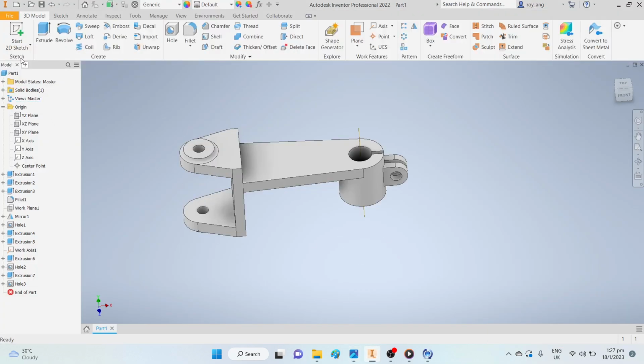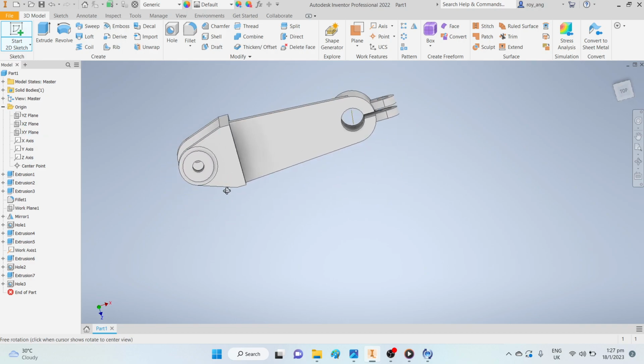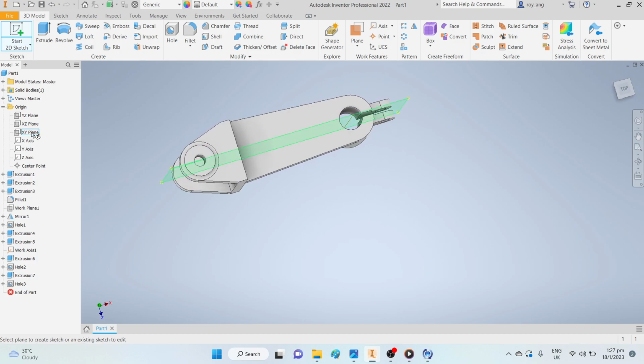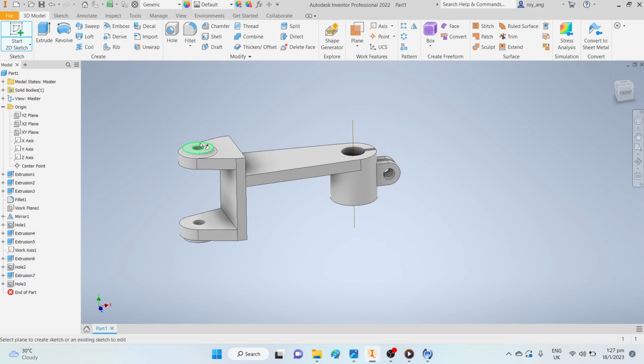How I will do it is I'll first create a sketch, and I'll sketch on the XY axis. Okay, the XY axis runs right through the center of the part, so that's where your work plane is, right? If you were to create a mid plane just to create the rib, you will lose marks. So please don't create extra work planes that you do not need. Okay, so you create the sketch and you sketch on the XY plane.